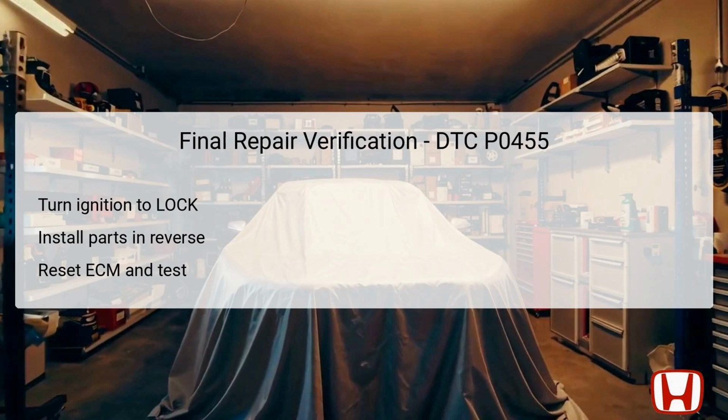Final repair verification is a crucial step following all troubleshooting measures taken for DTC P0455. First, turn the ignition switch to the LOCK (0) position. Then, install all components in the reverse order of removal, ensuring all parts are securely in place. Following this, power up the system by turning the ignition switch to ON (II).